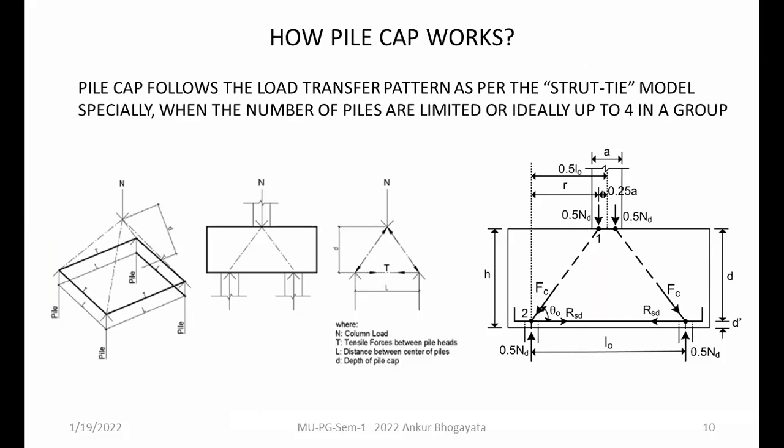So the question comes up: how does a pile cap work? They ideally work on two principles. The first principle is the strut and tie model, where you can see in some of the figures that it is assumed that the bottom part of the pile cap works under tension, and throughout the thickness of the pile cap, the shear force or ideally compressive force exists.